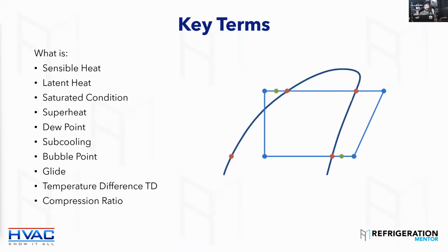And in a lot of cases, Trevor knows this, we've talked about this with scroll compressors. If they get warm enough, they can actually still run, but the scrolls disengage and they don't pump. And a lot of people get tricked and think the compressor's dead when it's actually not. It's just hot. The scrolls have disengaged. You put your gauges on, the pressures are equalized on both sides, but the compressor's fine. You just have to let it cool down, and it could take hours unless you have a hose on the roof to soak the thing.